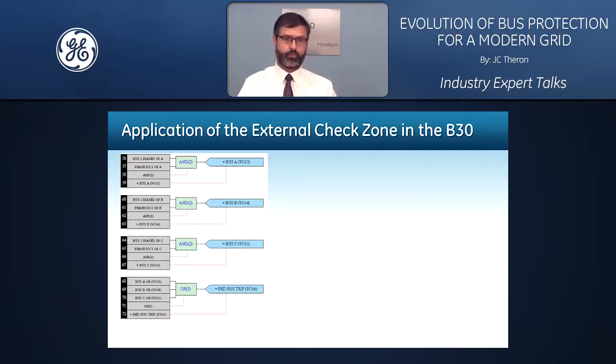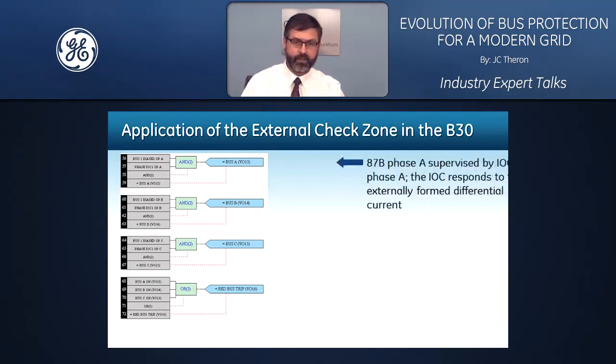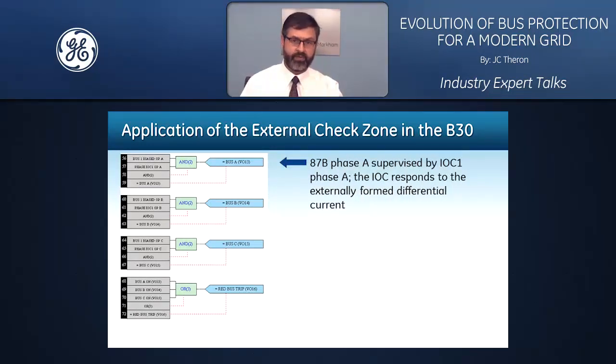And then the logic would look as follows. So first of all, the differential function, for example, the A phase, will be supervised with the instantaneous overcurrent of the A phase. And the instantaneous overcurrent responds to the externally formed differential current.